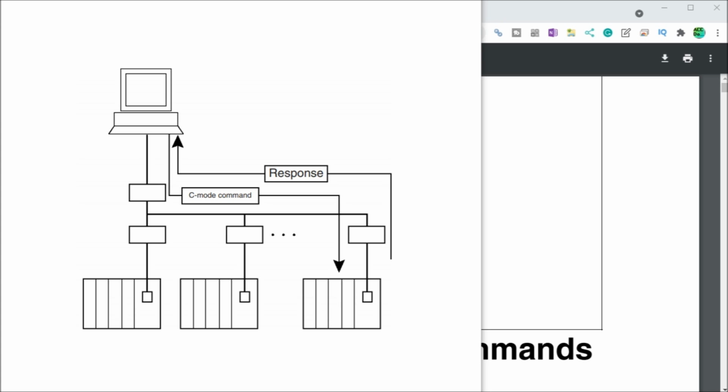And we will be connecting the Node-RED to the Omron CP1H PLC. A serial RS-485 interface will be used for communication to the industrial controller. We will be demonstrating reading and writing using hostlink or C-mode commands to the Omron.